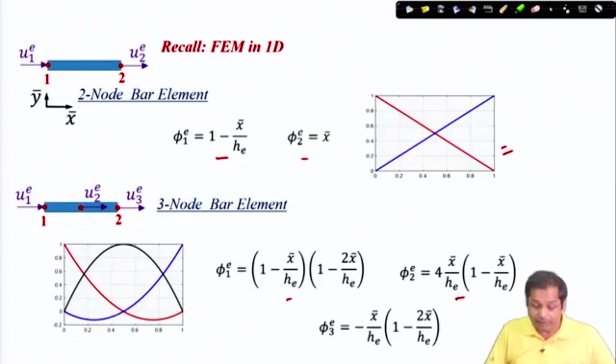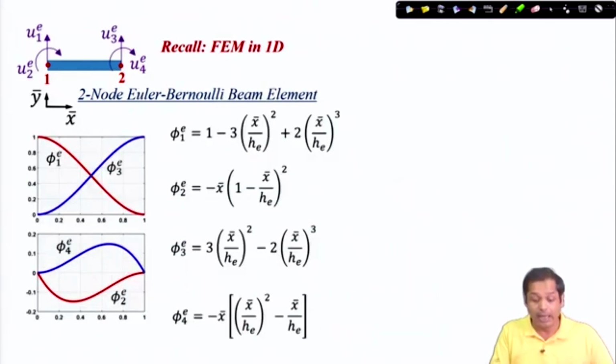Now there is a difference between the approach we followed while constructing these shape functions and the approach we followed while constructing those shape functions, and that is already discussed. Okay, in these shape functions we also approximate the derivatives. So the derivatives are also continuous at the node. So this is how the shape function is constructed.